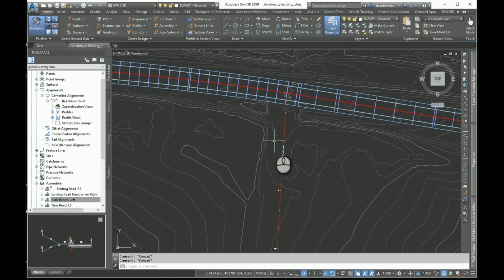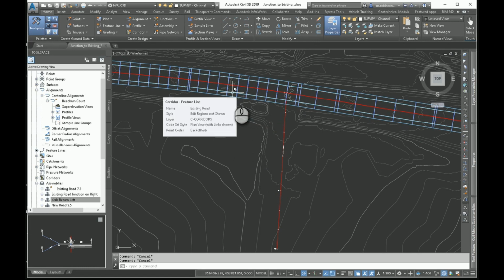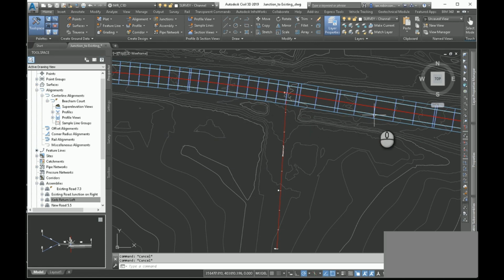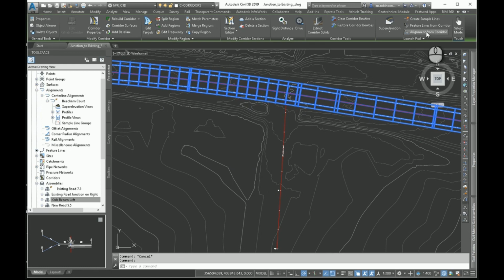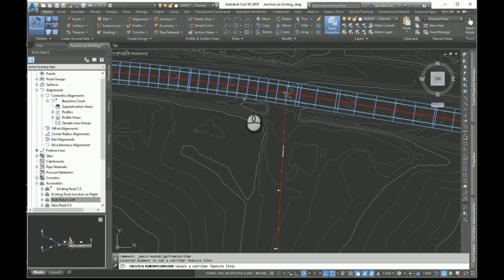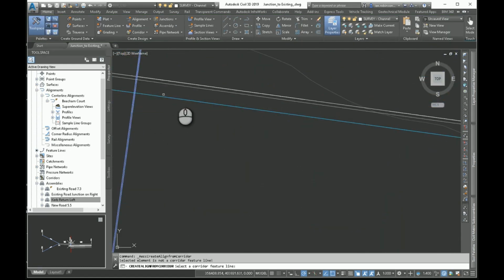What we need to then do is tie in our curb line. So our channel line that runs down both sides here, we need to tie into the channel line here. Well, the easiest way to achieve that is to extract the level information of the existing channel line. So I'm just going to select my corridor, and if you pull out of the corridor an alignment and go and pick that channel line,